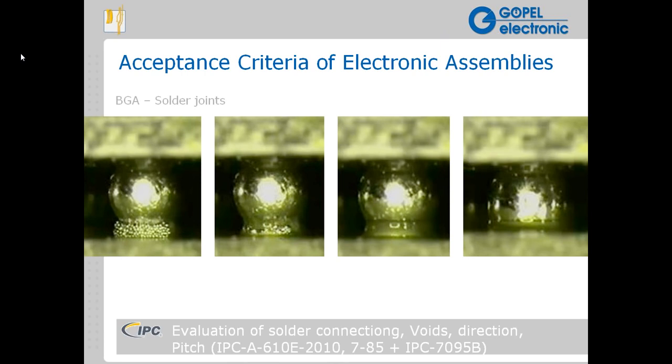Patrick, anything to add there? Yes, and Philip, you are absolutely right. It is about an indicator of your production process. So what you test here is not only failures and passes. It also tells you how your oven profile is. If you have a solder joint like in the first image here, then something is wrong with your temperature or your soldering mass.